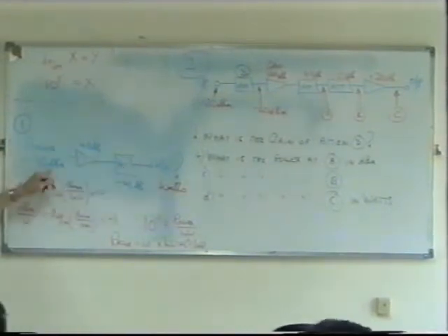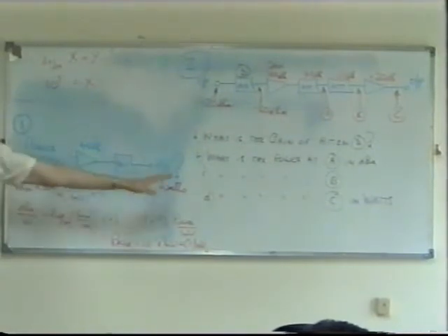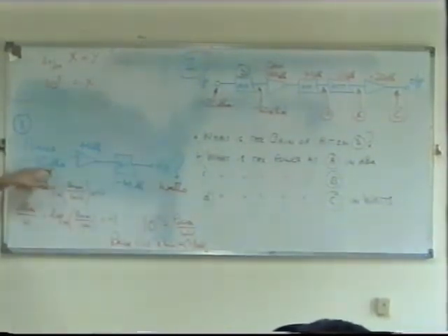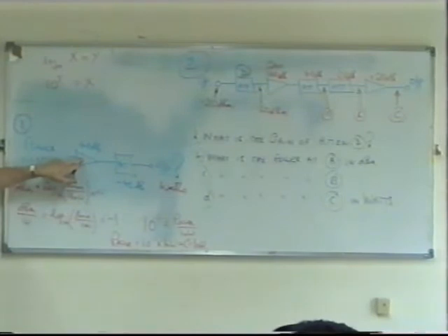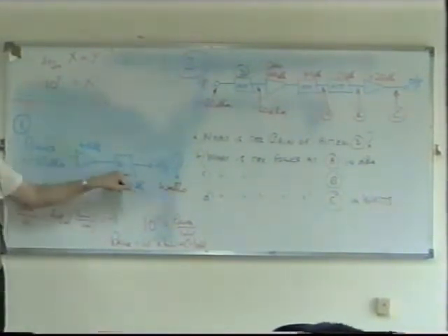But because we're already dealing with logarithms, we just add and subtract. So a plus 40 dB gain and a minus 40 dB gain more or less cancel. Whatever the amplifier is supplying, the attenuator is attenuating. So we end up with the same as we begin with. The output is the same as the input, minus 10 dBm.